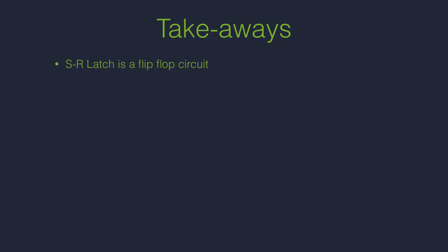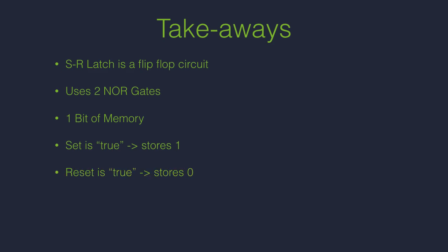Let's do takeaways. Ready? S-R latch, it's a flip-flop circuit. It uses 2 NOR gates. It's storing 1 bit of memory. When the set is true, it stores a 1. When reset is true, it stores a 0. You just learned how memory works.